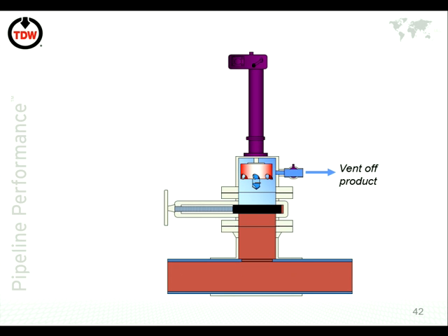What I mean is for the subsea operation, for the offshore operation, how can we purge? On a subsea, you just run a hose down. It's obviously this is more covering the hot tapping, but I have included a slide at the end which actually shows a subsea hot tap operation, and I'll show you it. It follows exactly this principle. The only difference is that where you have a very short pipe here, you will have a very long hose which will go to the surface. So they'll actually take it to the surface, and they will do it on a vessel.